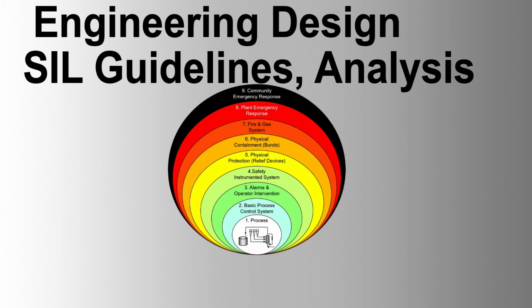6. Once a component has failed in one of the possible failure modes, it cannot fail again until it has been repaired. 7. Fail-safe and fail-dangerous states are treated as absorbing states, meaning they are not repaired, to simplify the modeling effort. 8. Systematic failures are neglected. 9. The evaluation time equals the functional test interval or mission time, typically 1 year. 10. Power supplies are not considered in the first two examples. 11. The beta model is used to treat possible common cause failures.